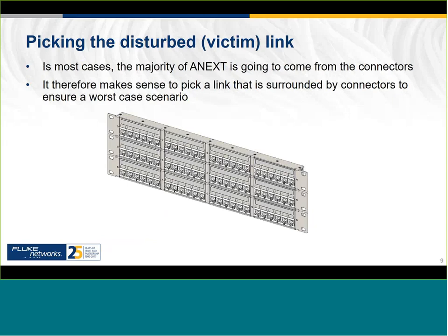So what do we actually need to look at when we do testing? In reality, most of the Alien crosstalk is going to come from the connectors. So it makes practical sense to pick links that are surrounded by connectors to ensure the worst case scenario.